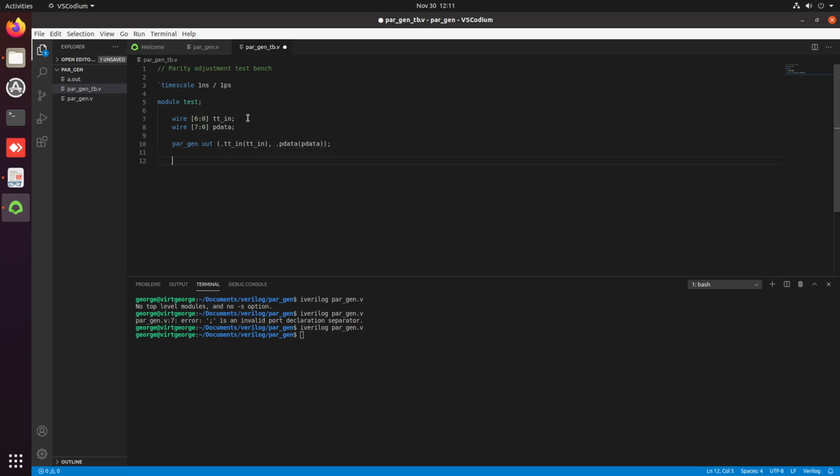Now the main part of my test bench. I need a counter. So actually, tt_in, which is my input, will be of type reg, because if I want to make a counter, it's much easier with an always. So I'll make my counter here, always, and every 10 nanoseconds, for example, I will increment tt_in +1. That will make tt_in increment constantly to reach all the values.